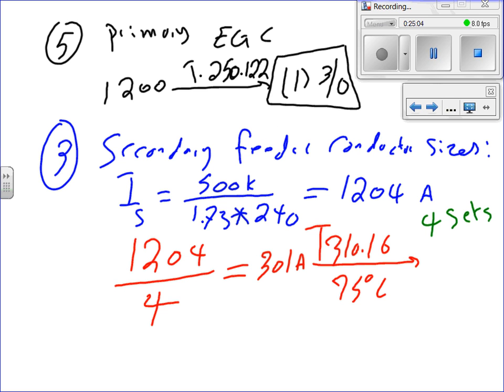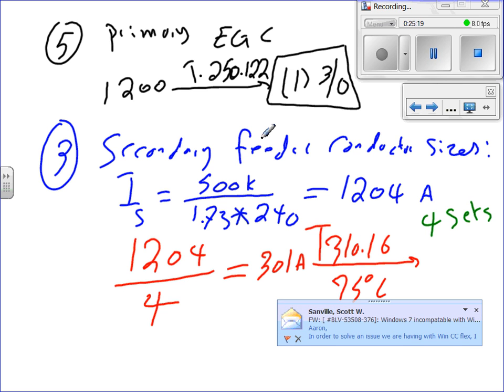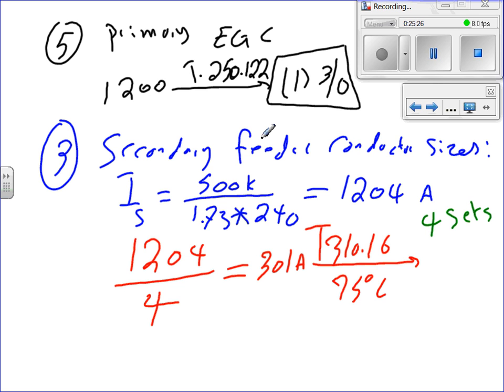Why 4 sets? Chad said so. Of how many conductors? We're sizing now, we're only sizing at the time. It's a Y, so literally I need 4 conductors. But because the amps are so high, I'm sizing for this transformer. I'm going to size the 3 conductors first, and then I'll come to the neutral. Why? Because the amps are higher than 200. Okay, so 3 conductors. What size?